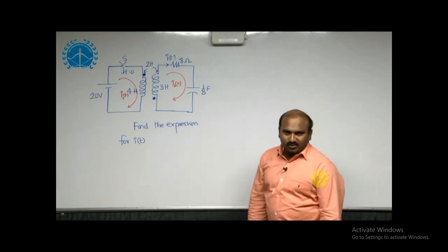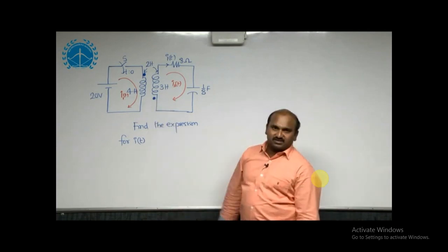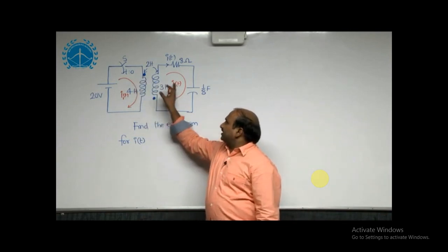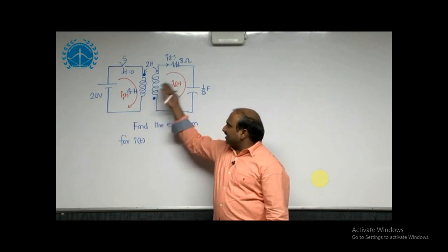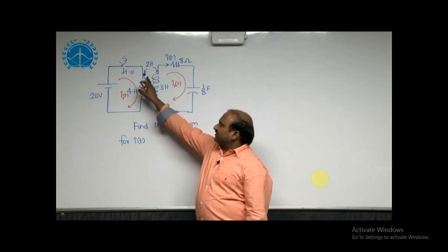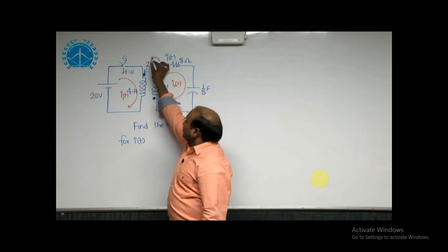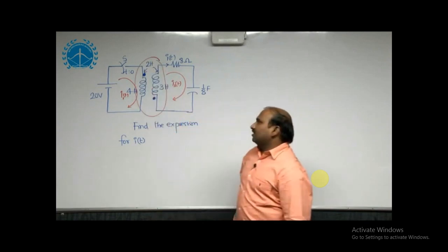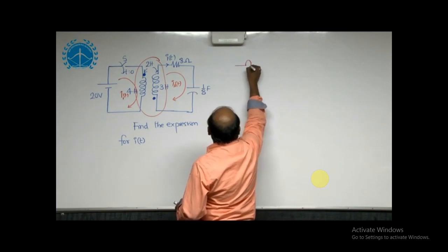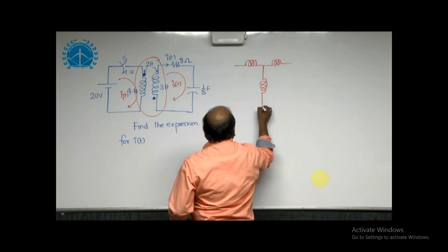After t equal to 0, this is a coupled circuit with mutual inductance. As per the dot convention, I1 is entering and I2 is leaving as per the current direction I have considered. I1 I have taken clockwise, I2 also clockwise, where both dots are entering. That's why when you define the equivalent circuit of this coupled circuit, when the two dots are entering, I can define the T equivalent circuit in the S domain. This is the equivalent circuit.